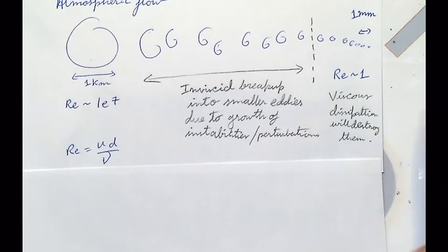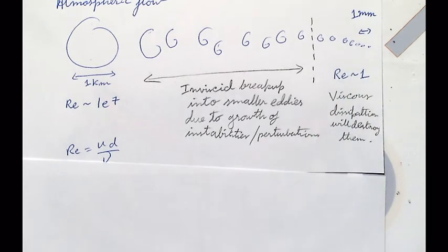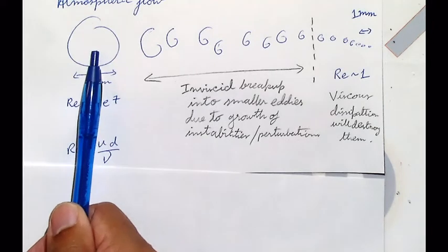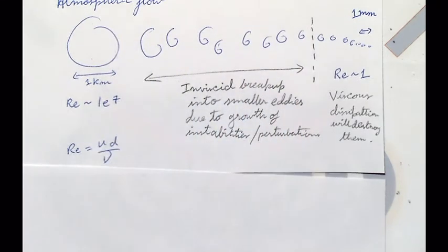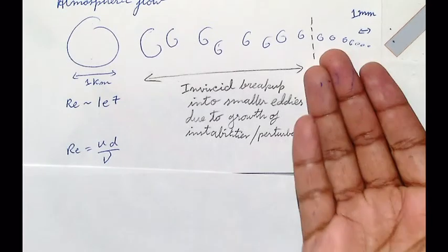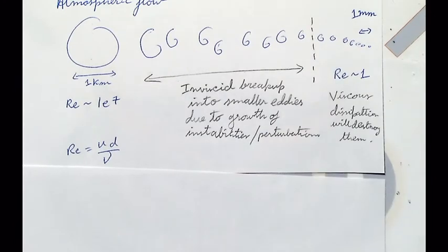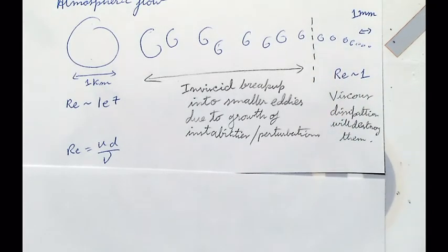They would not break down anymore, they would not dissipate their energy, because again, the Reynolds number is not small enough yet. But if there's a mechanism that keeps pumping in energy at the large scales, your system will eventually get saturated with a lot of kinetic energy and blow up. Right? Physically, that does not happen exactly because it gets dissipated. But in simulations, you're not restricted by anything. You can get rid of these small scales. Okay? How do you do that?